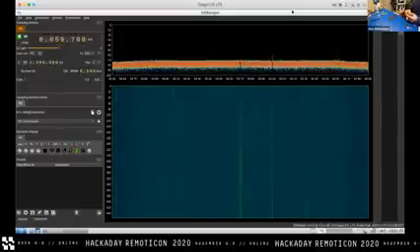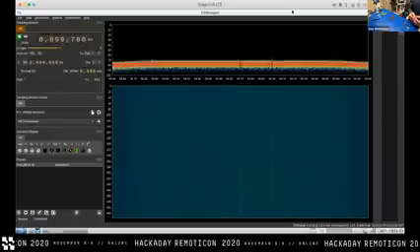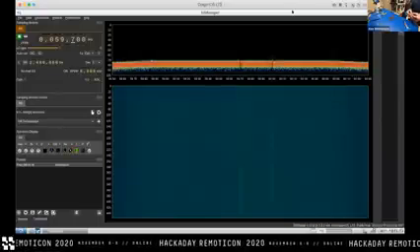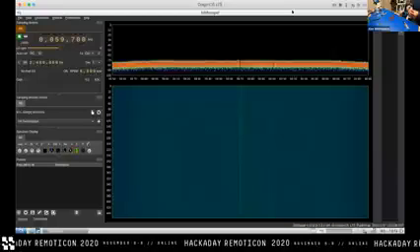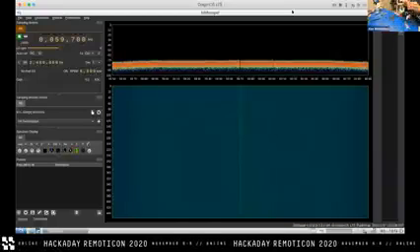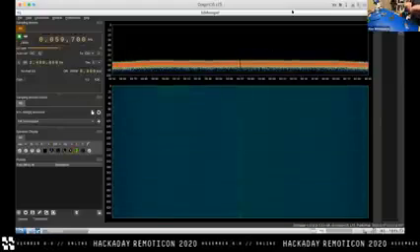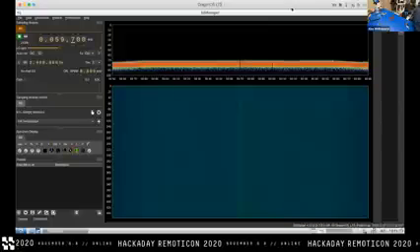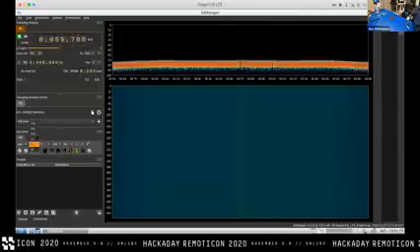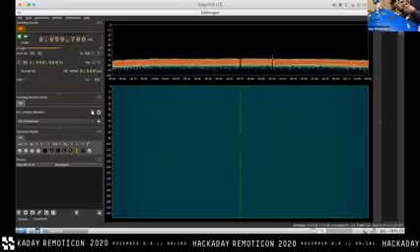And because we've got the spectrogram view here too, seeing in the waterfall diagram what's going on makes things a little bit clearer when we have such thin FFT bins on this particular screen. Actually, just for giggles, I'm going to make the FFT a little shorter. This will make the peaks a little bit wider and more obvious.